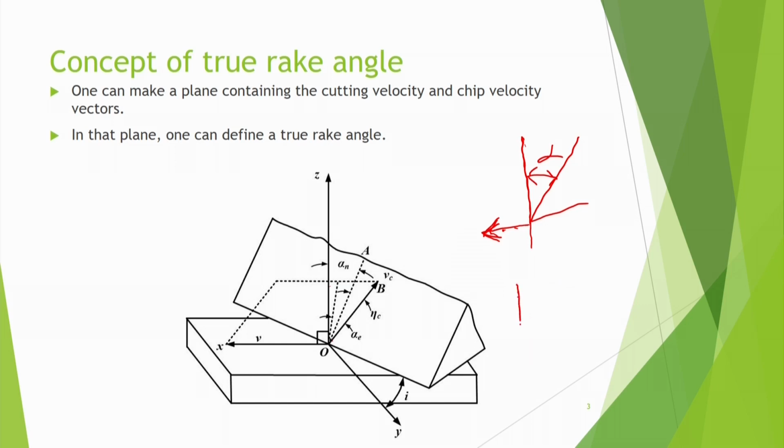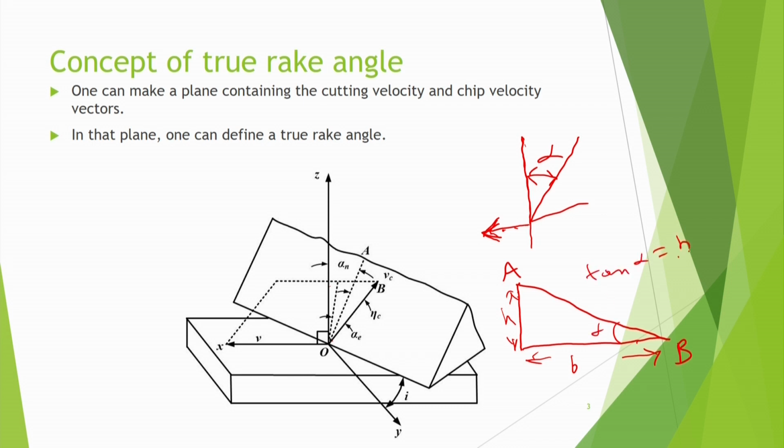Usually, suppose there is a sloping surface, let us say AB is the sloping surface. If I ask you to find the slope of this surface, it is very easy. When you move from B to A in this direction, you lift up vertically by a height h, and you go some distance in the base direction b. So we say tan alpha is equal to h by b, and we talk about only one slope.